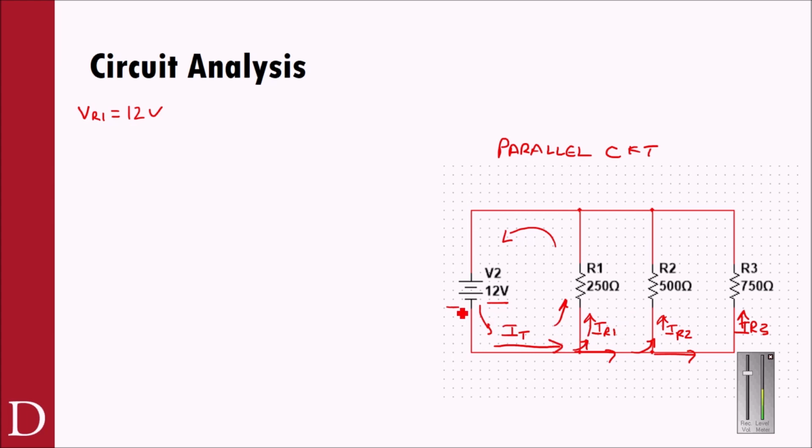power device I see, then that power device R1 is going to consume a full 12 volts, which means that, guess what? VR2 would do the same thing, and VR3 would do the same thing. So in a purely parallel circuit, those devices are each going to consume 12 volts. And then it's very simple. You know, we do E equals I times R.